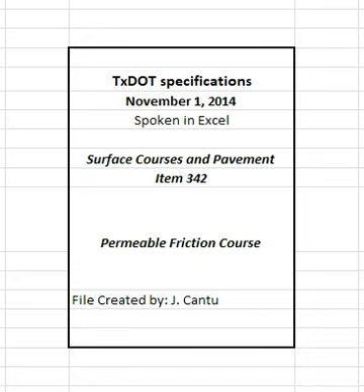4.9.5 Recovered asphalt dynamic shear rheometer, DSR. The engineer may take production samples or cores from suspect areas of the project to determine recovered asphalt properties. Asphalt binders with an aging ratio greater than 3.5 do not meet the requirements for recovered asphalt properties and may be deemed defective when tested and evaluated by the construction division.